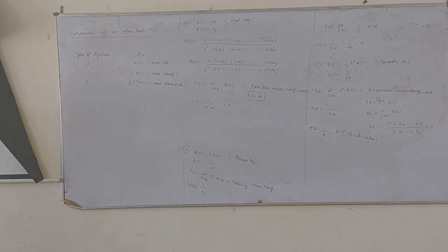If the order of the input is the same as the type of the system, then the steady state error is finite.